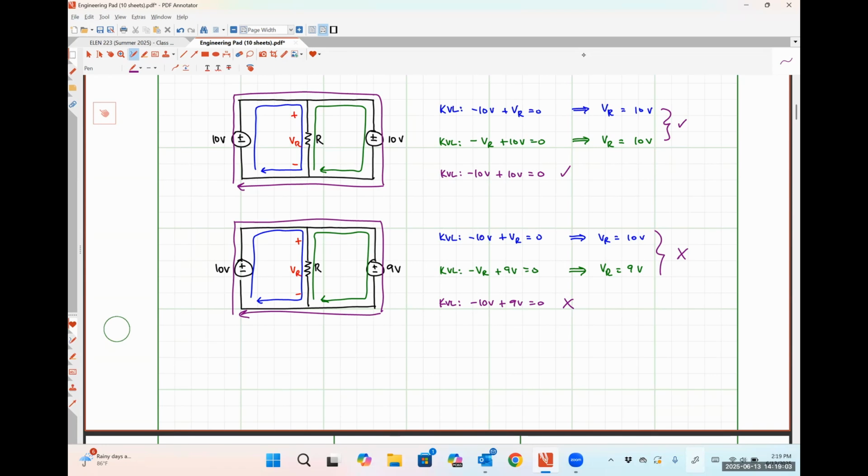So what's happening here is effectively because we assume that our wires are short circuits, we are essentially accidentally violating the laws of physics. In a real system, these wires would have some amount of finite resistance, and so this system would actually balance itself out. What we would usually find is that those wires are going to wind up carrying a heck of a lot of current, so much so that we would probably see sparks and they would heat up enough to cause the insulation to melt, but we could actually realize this system.